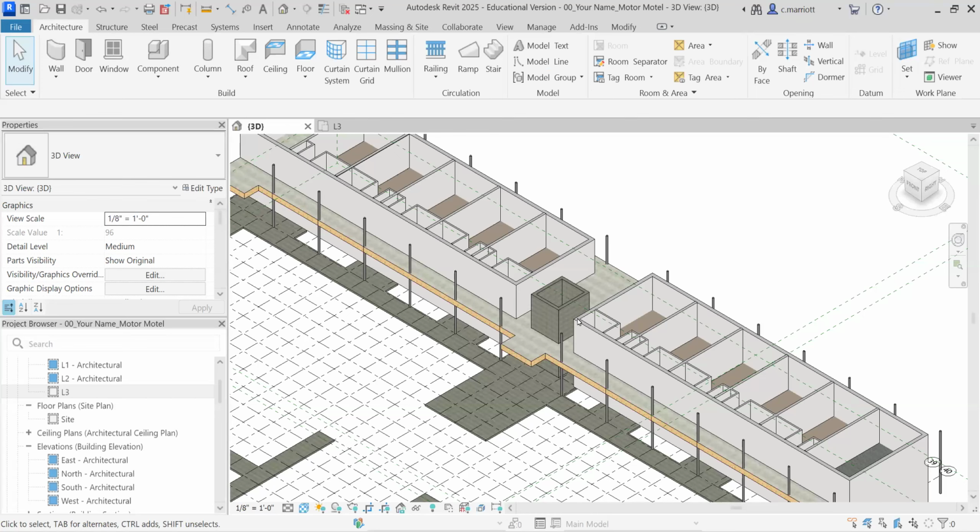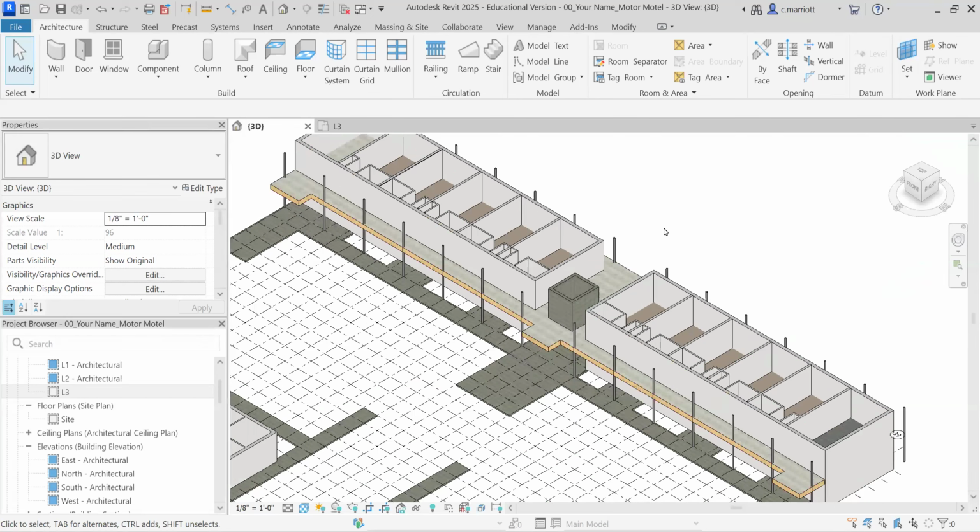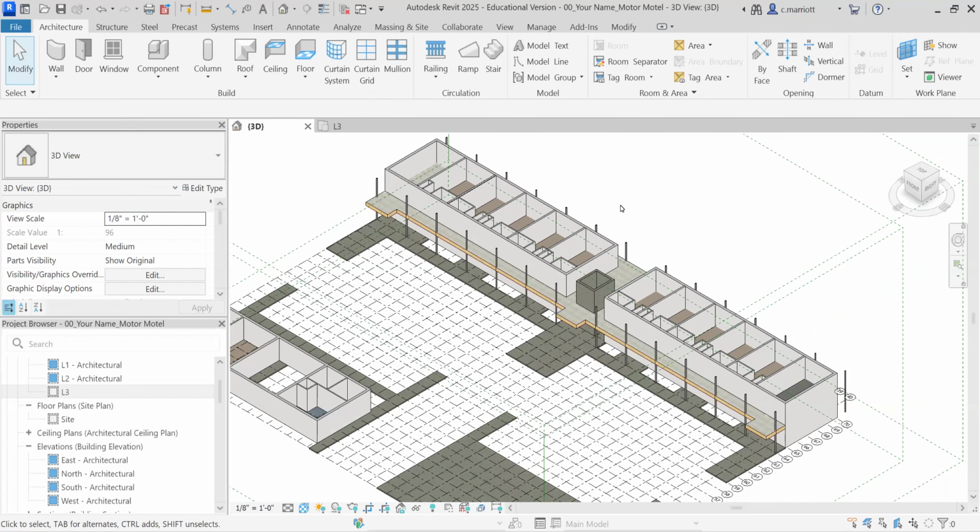So in this video, I will go over how to bring in a flat roof. Now, we're actually going to use a floor assembly for the purposes of this. Just to give you a very quick overview on flat roofs: technically, they're not flat. They have a pitch. They typically pitch towards the middle of the roof, where you have some roof drains that collect water and bring it down and out towards whatever sort of sewer system the property has.